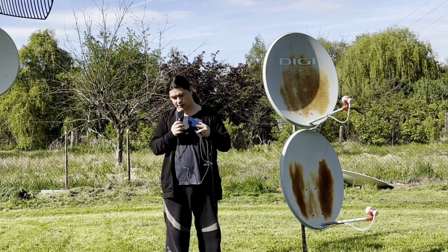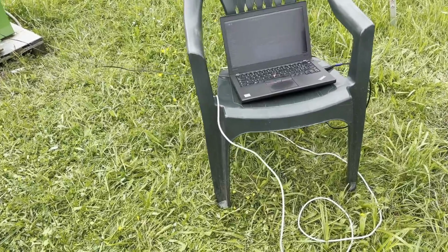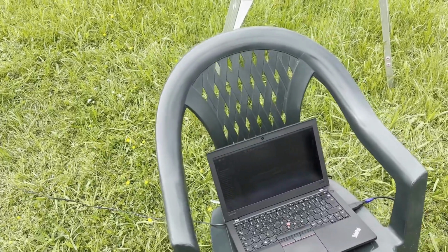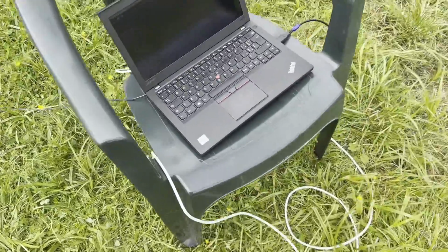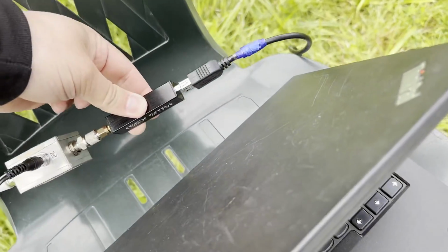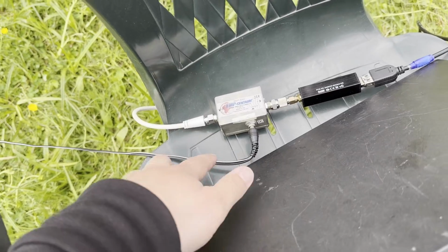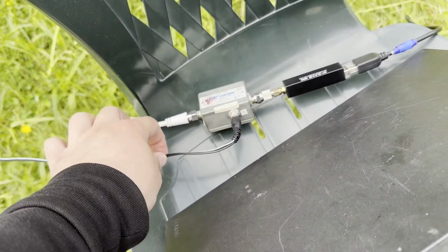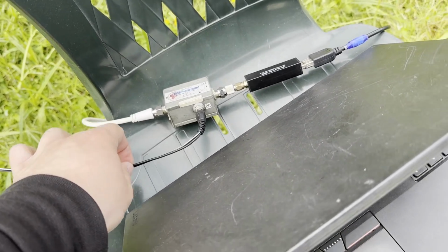I am again using an off-the-shelf bias T power injector, again intended to be used with LNBs like that. It's very convenient because it just has a female barrel jack connector, and I'm using a wall power adapter that in the video example is actually connected into the fridge over here. Don't think about that too much. We just have wall power, 30 volts converted into 12 volts, being injected into the coax and sent to the LNB. That's how we are powering it.